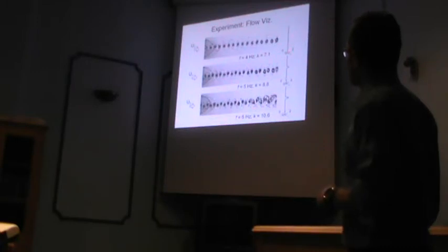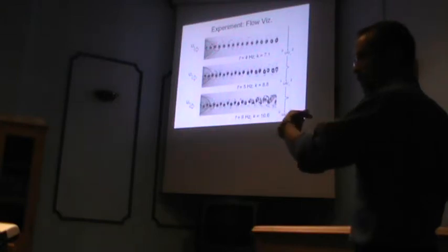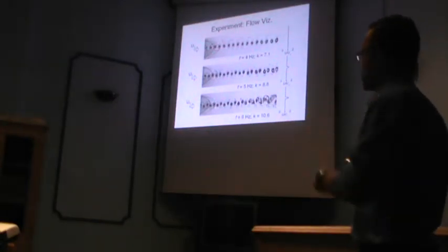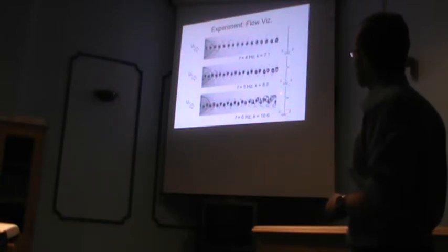And that's actually the mean velocity. So this big U means it's an average velocity, and small u means it's in the streamwise direction. So this is the mean velocity profile measured in the wake one chord downstream for these 3 different conditions, normalized by the free stream velocity.